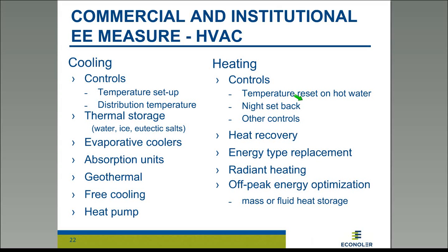In terms of HVAC, there's a large quantity of options for energy conservation. So basically, we look very often at controls. Can we do a temperature setup, looking at the distribution temperature or the pressure of the distribution duct for the ventilation system? Thermal storage offers a lot of opportunity, and I think it's still something that is not used enough in most applications, because we see that in several countries right now the price for air conditioning systems is dropping rapidly, and the living standard is also increasing rapidly. So the combination of the two factors makes the AC load just boom in several countries, and that drives the peak demand for most countries.